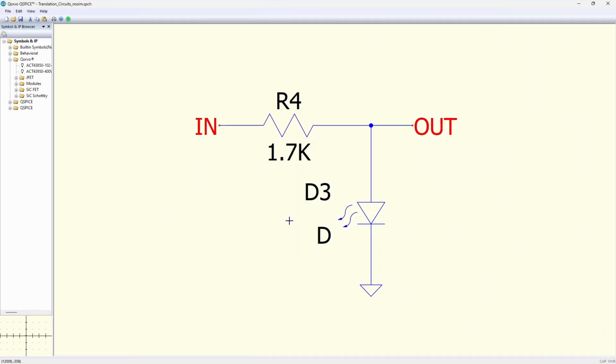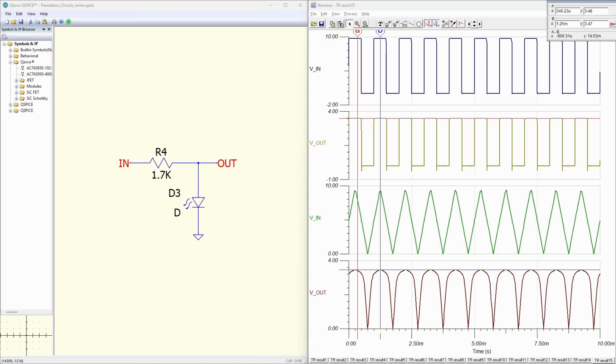Now, if you don't want to use a positive side clamp because you're worried about the current going back to your supply, then you could use a ground side clamp. In this case, I've selected an LED that gives me an output voltage of about 3.5 volts. You can get LEDs that go all the way down to about 1.8 volts, and they go up to around 4 volts. So it kind of depends on which LED you pick out specifically for the application.